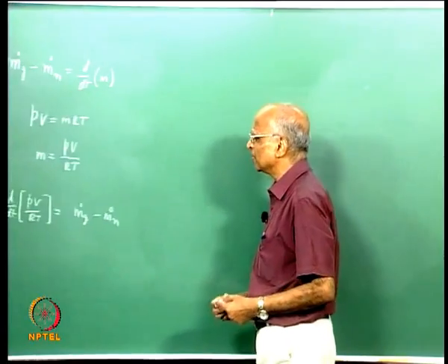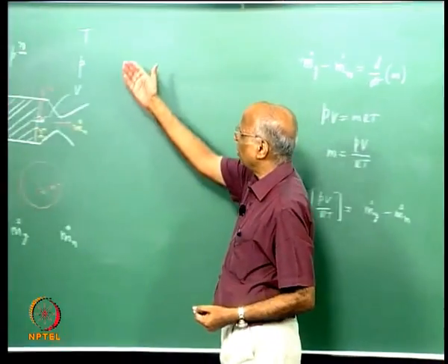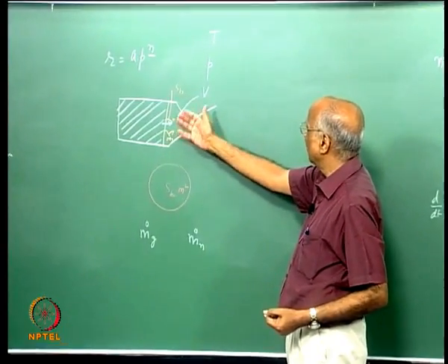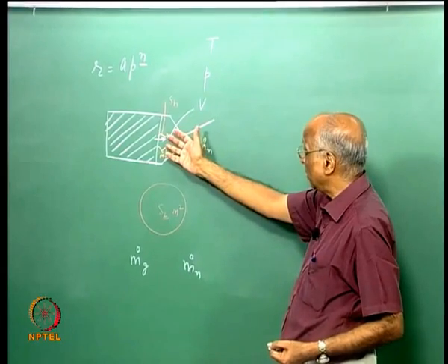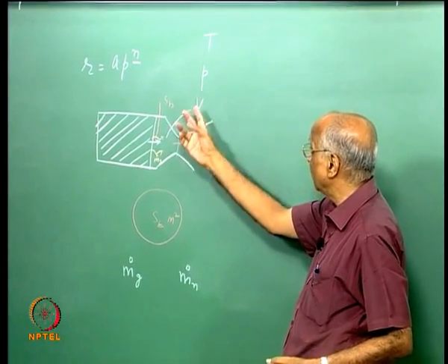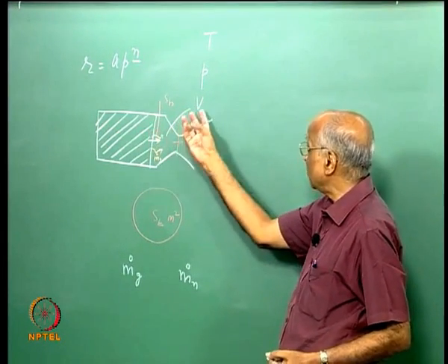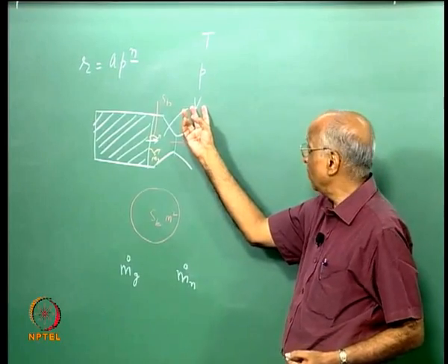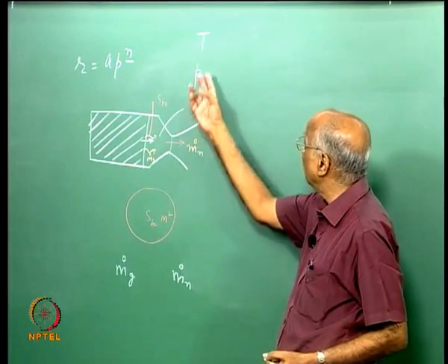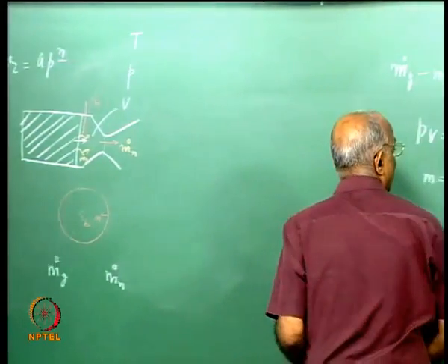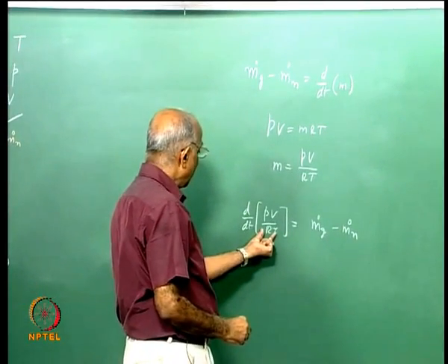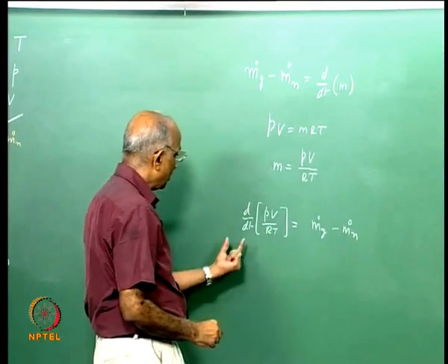What are the variables? Temperature is a constant, the flame temperature. Pressure could vary, and as the propellant regresses, the volume varies. Therefore, I have two variables, pressure and volume. The flame temperature is a constant, and R is the specific gas constant, so it is constant.